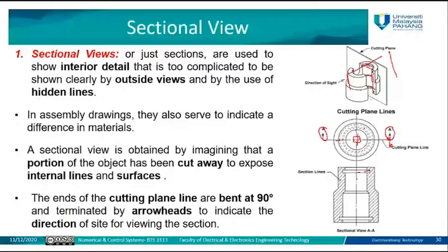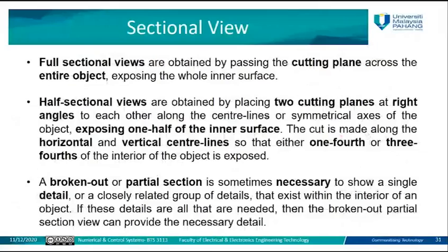So you can take a sectional view for this part, for that part, and for that part. Each one has a sectional view. So you can find it for each half of the inner surface here. Also you can find it for 1/4 or 3/4, because they will be identical. For example, if you have a cylinder and you cut it on 4 sides, this part is similar to that part. So either you represent it by 1/4 or 3/4 for the sectional view.